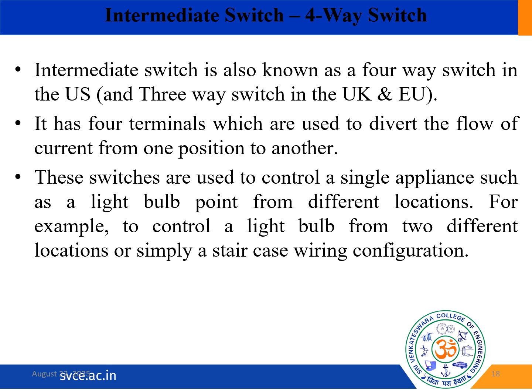These switches feature four terminals, allowing them to redirect the flow of current between different pathways. Typically, in conjunction with two-way switches, they create flexible lighting control setups. That's the main advantage in using this type of intermediate switch. Here we have some varying applications where we can use intermediate switches. This type of switch can be used in staircase lighting, so the light can be controlled from both the top and the bottom of the stairs. Also in hallways or large rooms, it can operate a single light from multiple locations.